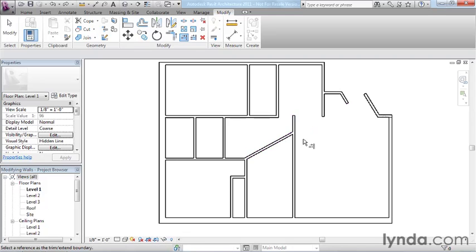Okay, well, it knows because when you select, you pick the side of the wall that you want to keep. So if I select here and then here, it will extend out to that location. If I select here and click here, it's going to keep the part on the right. If I click here, it's going to keep the part on the left, like so. So depending on how you select your object, that's going to determine which condition you get. So pay attention to that when you use the Trim Extend tool.